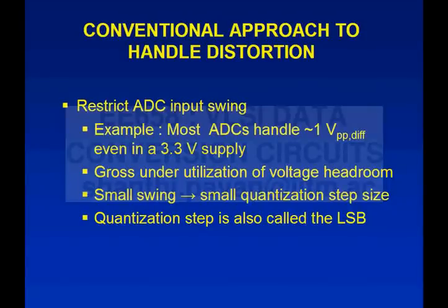If I know that I'm going to be designing a 6-bit flash converter, for example, I know that the signal to quantization noise ratio can't be any better than about 37-38 dB. So if I say my threshold of pain as far as distortion is concerned is some number lower than that, and we all agree, for example, that 45 dB is good enough as a THD number for the track and hold, then this 45 dB is about 10 dB lower than the signal to quantization noise ratio that you would get for an ideal converter anyway. Okay, so it's probably not too bad.